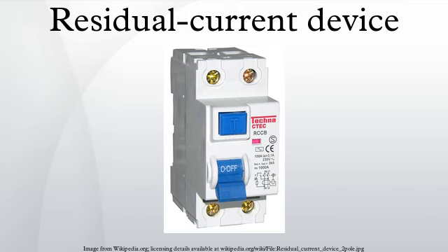The diagram depicts the internal mechanism of a residual current device. The device pictured is designed to be wired in line in an appliance power cord. It is rated to carry a maximum current of 13 amperes and is designed to trip on a leakage current of 30 milliamperes. This is an active RCD. That is, it latches electrically and therefore trips on power failure, a useful feature for equipment that could be dangerous on unexpected re-energization.